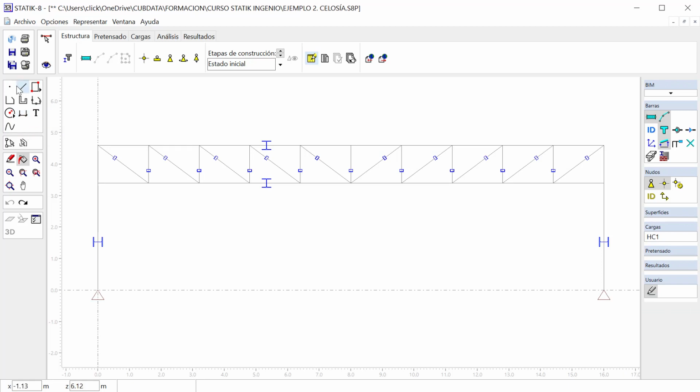These are elements that we can use to write texts, to help the documentation of the drawing, but what is usually used is the annotation. Then click on the dimension lines, and from there, it is very easy. Just follow what the program says. Select the X or Y direction, then you say X, for example, this one here. Where do you want to put the dimension? Here. And from where to where do you want to annotate? From here to there. And that's it.